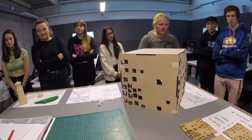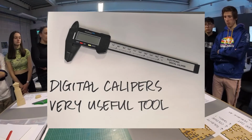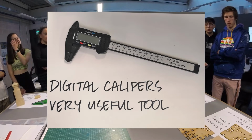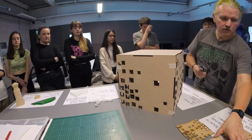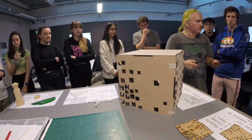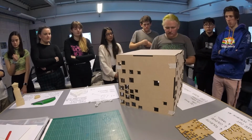So this is a really useful tool to use as well, because when you look at a catalogue or whatever, that's 6 millimeter MDF, but it's not. It's 6.1 millimeters, and that's advertised as 3 millimeter MDF, but it's not. It's 3.2 millimeters. So we've got the accuracy in the CAD, and you have to allow for that, because otherwise it could be way too tight once you try and put it together. So really useful little device.